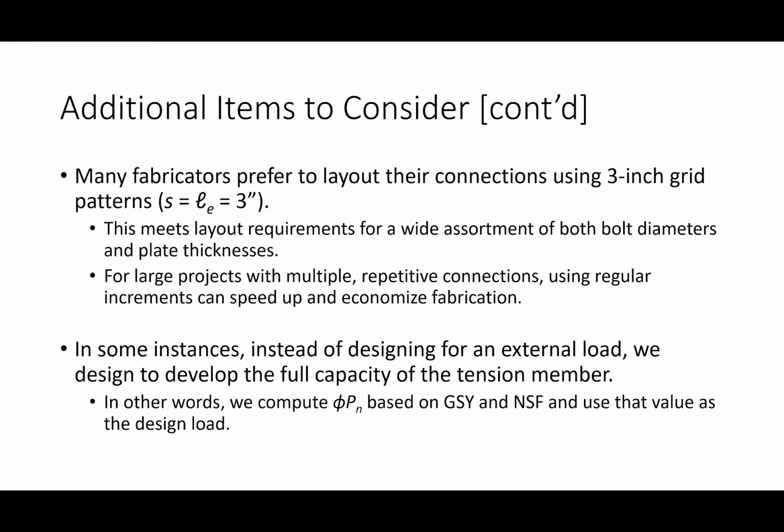Many fabricators do prefer to lay out bolt connections or bolt patterns in a 3-inch grid. What I mean by that is using a bolt spacing of 3 inches and an edge distance of 3 inches.